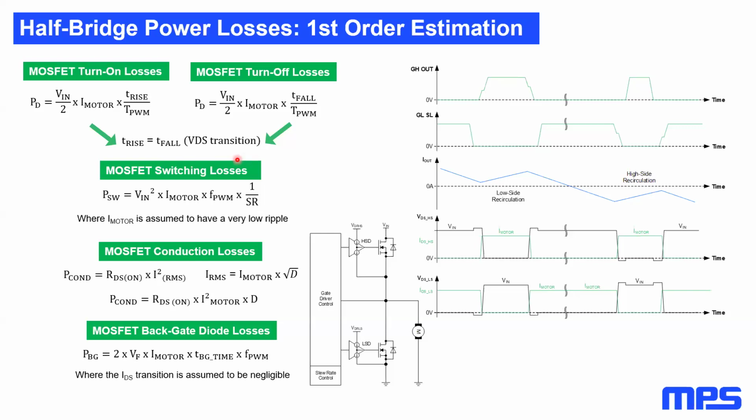This means that when we turn on the low side, the body diode will be carrying the current, and the voltage at the switching node, which is basically the VDS of the low side, will be minus 0.7, minus 1 volt, depending on the current and the body diode temperature.